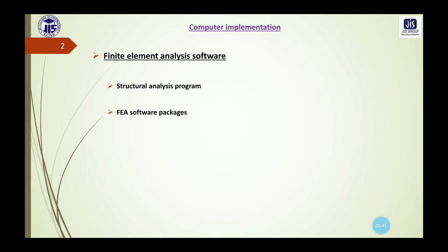What is this SAP4 actually? This SAP program has 9 element types, and the structural systems to be analyzed may be composed of a combination of these elements. Now the capacity of the program depends on the total number of nodal points of the system, then the number of eigenvalues which are needed in the dynamic analysis, and the main memory allocation of the master array. The concepts of the node or nodal points and the elements have already been discussed in the earlier lectures.